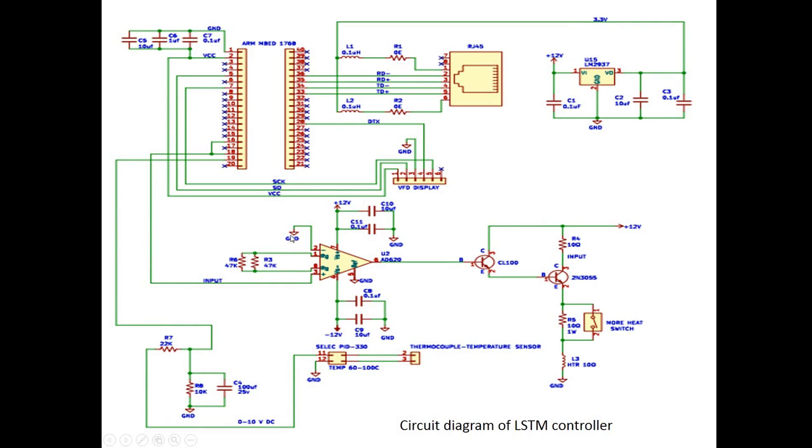So this is a circuit diagram here. This is that microcontroller again. This is the Ethernet port, and this is the heater. This is a 100 ohm heater, which is powered from this microcontroller device, and the microcontroller is commanded over this HTTP server using one command. So reading the temperature is one function, and there is an HTTP GET command for writing into the heater.